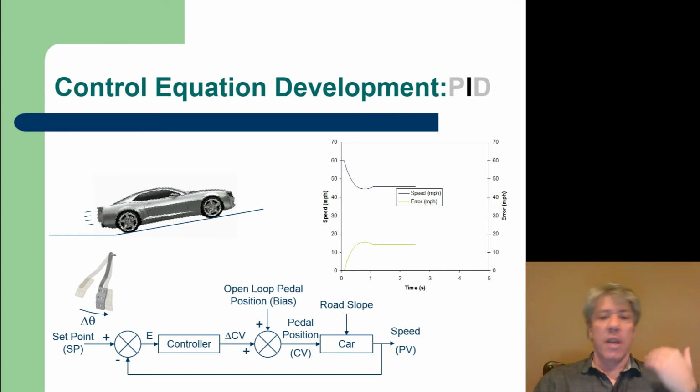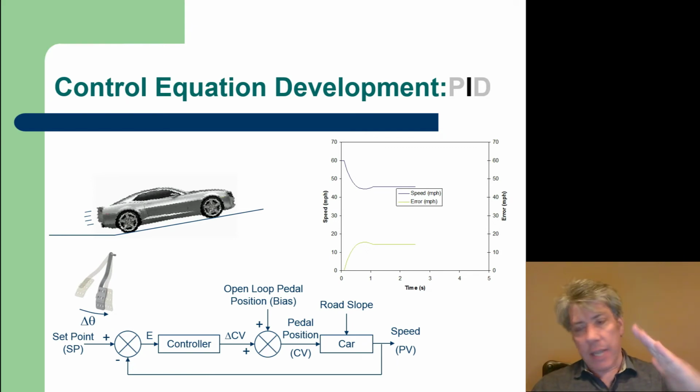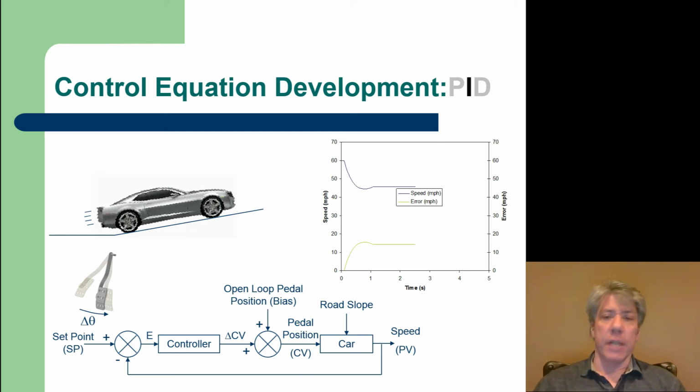The controller has integrated over time, and it's added up all of this error, and it's decided, hey, the pedal has to be all the way down, but the car is simply not capable of climbing the current hill at 60 miles an hour. It's saturated. This is controller saturation because the control variable is at a limit. It's at the positive limit. Now it could be at the negative limit too. Both the positive and negative, or the zero limit, are valid limits. But in our case, we're trying to climb and we just can't. We can't maintain 60 miles an hour because this engine with this car simply cannot do it.